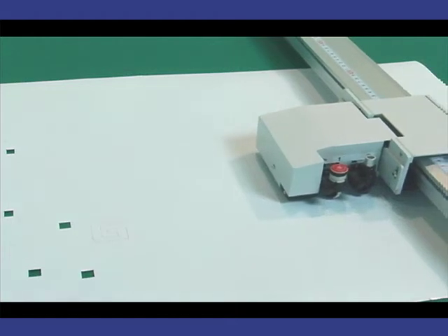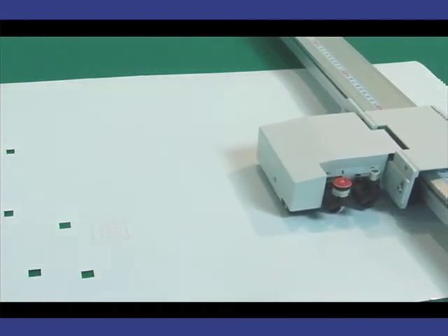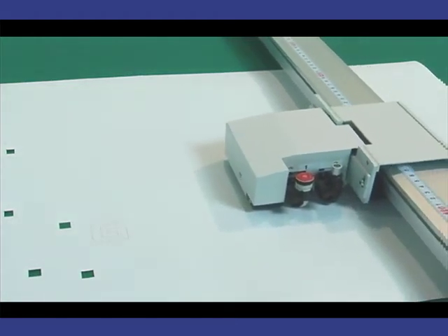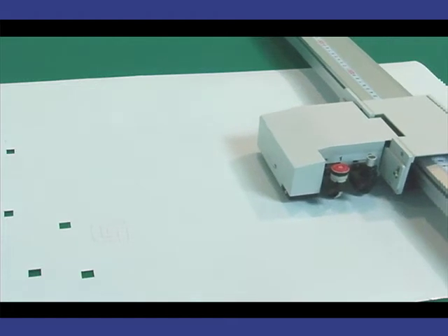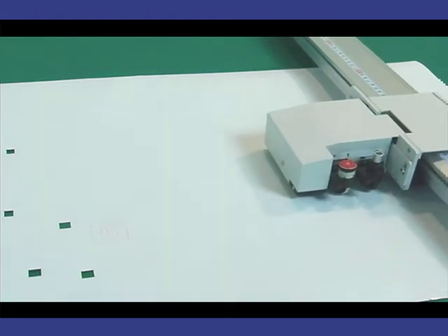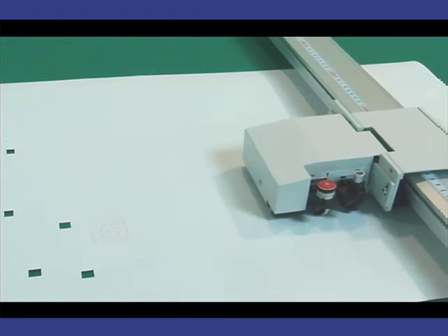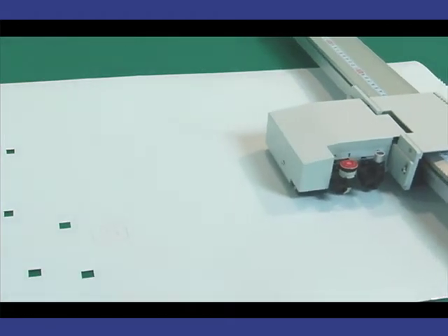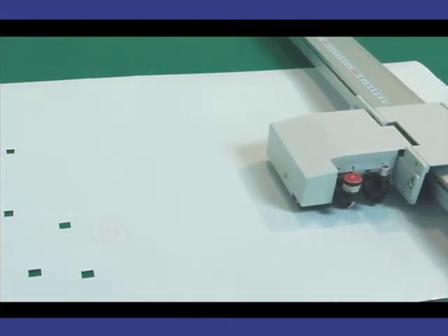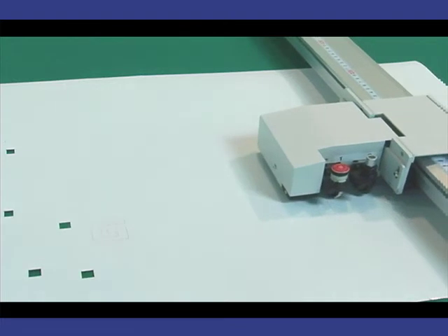One thing to note is that when pausing the plotter, don't expect it to stop on the dime, so to speak. The plotter will actually wait until it finishes the current object and then go ahead and stop. The reason for this is that it's actually a protection in that the blade can be adjusted during that pausing, causing a possible tiny gap in the cut line at the point where the plotter was stopped.